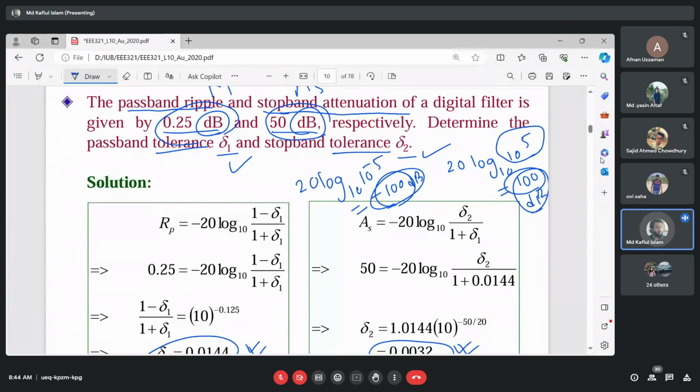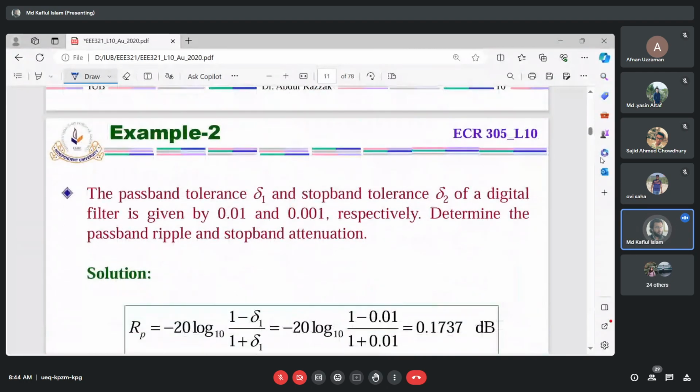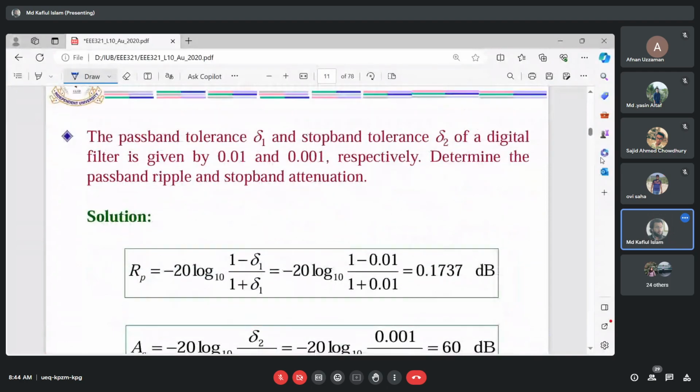And relative specification also gives you the idea of how good it is with respect to the maximum value. So this is another part. Since we are normalizing the value with respect to the maximum, as well as talking in decibel or log scale, we can see the physical interpretation of that number very easily. So this is one of the reasons why we move to relative specifications from absolute specification.